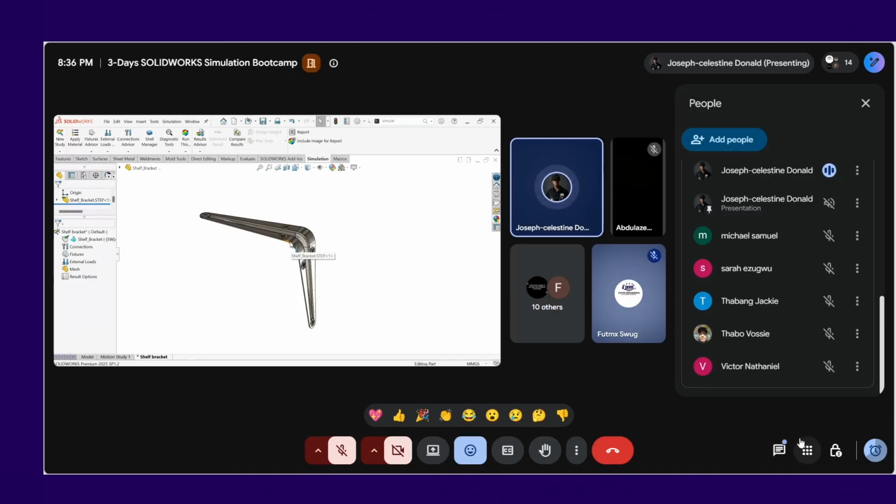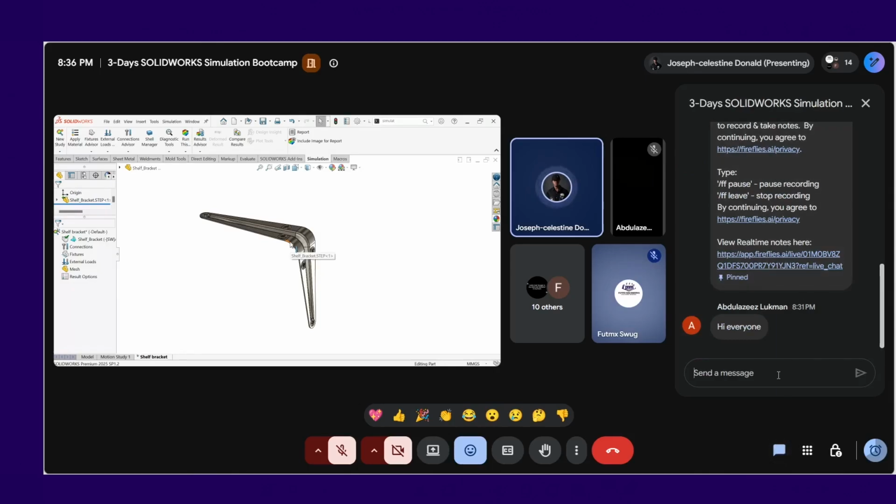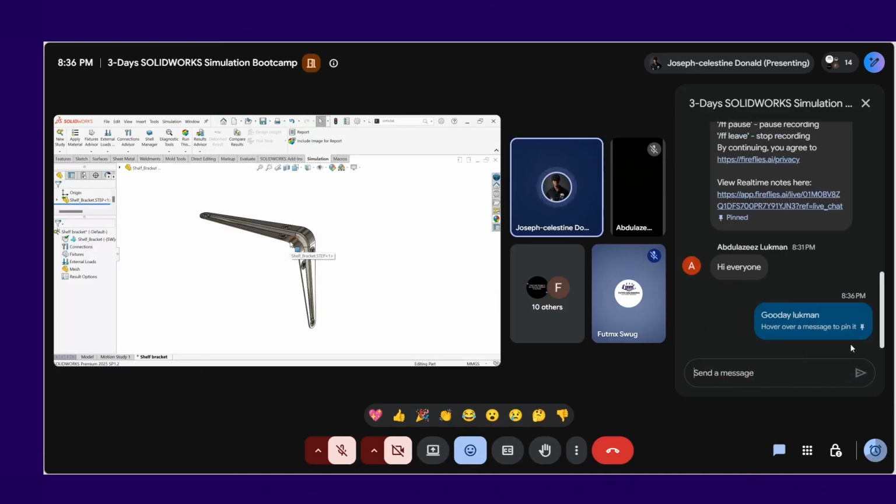Fixtures basically define, physically, where you are constraining your design to. Where are you putting it? Are you nailing it? Are you using gum, leaving it there, holding it with magic? However you decide to hold it, it's called a fixture. Sometimes people get it wrong, using a fixture that mimics gluing when they're actually nailing, or when they're just sticking it there with some superpower.